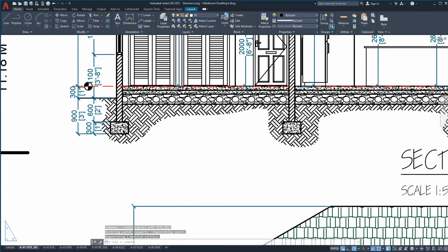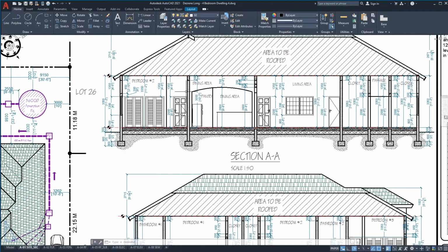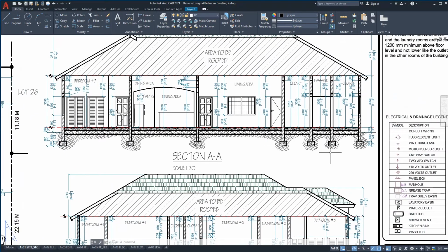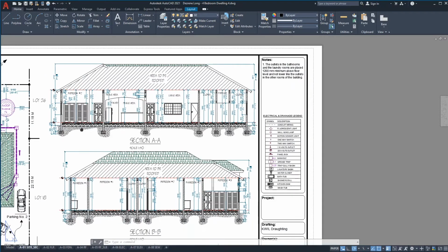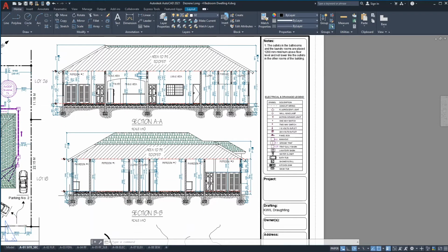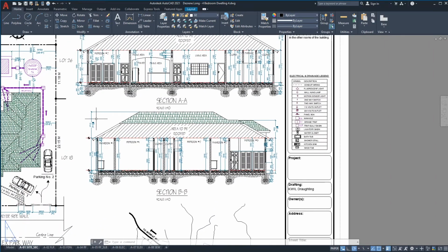elevation shows. It also shows the foundation depth and so forth for each wall. It shows you how the foundation is situated. All of the vertical heights are shown on this plan, so you can see inside of the building. This component, or this particular drawing, the sectional drawing, is very detailed and is quite necessary.